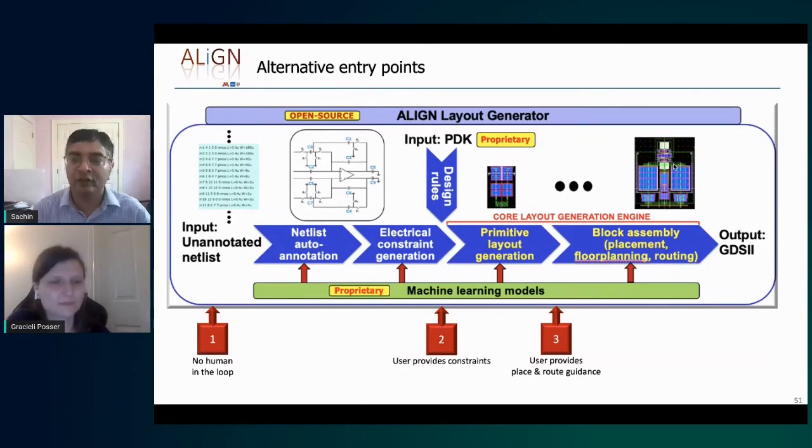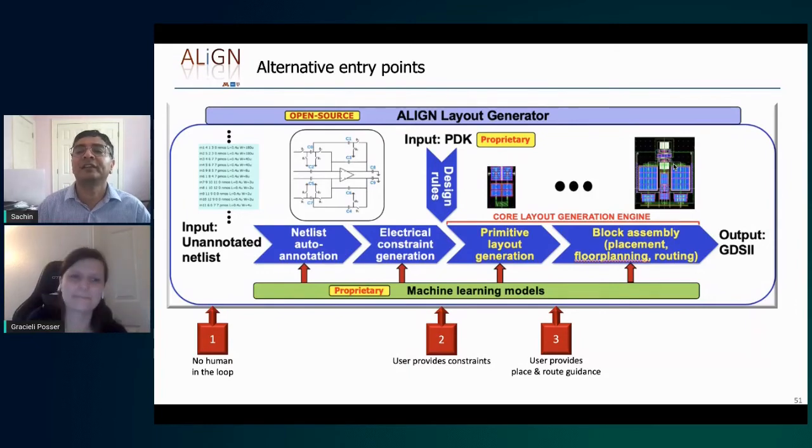We actually worry a lot about reliability issues, which are somewhat related to thermal issues as well. So if you have, for example, a wire that carries too much current and could be an electromigration hazard, and that's particularly important in analog circuits that carry steady DC currents, then we handle those. I see, nice. Yeah, you are the electromigration guy, so I'm pretty sure you want to let those pass.